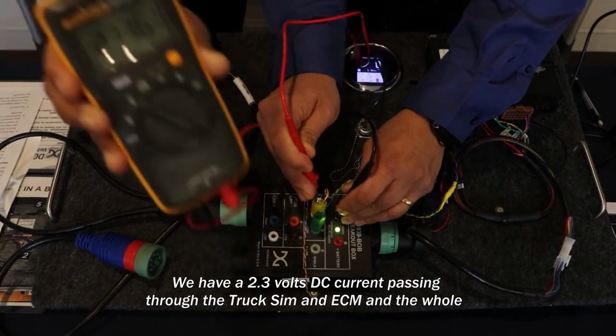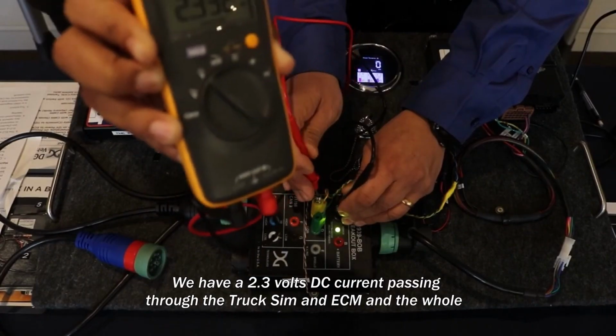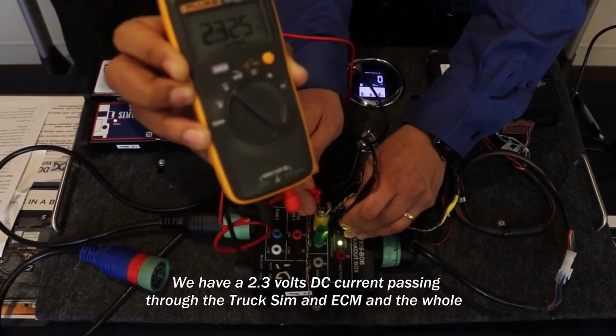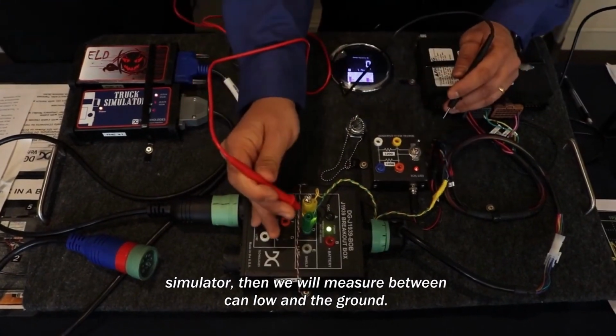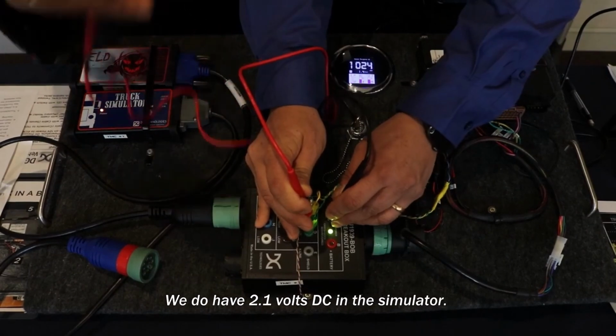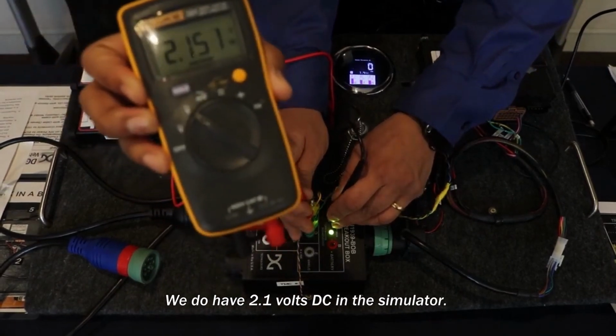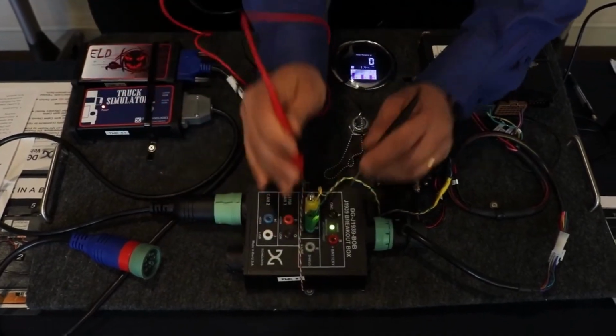We have 2.3 volts DC passing through the truck sim, ECM, and the whole simulator. Then we will measure between CAN low and the ground. We do have 2.1 volts DC in the simulator.